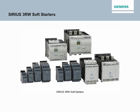Some soft starters, such as the Sirius 3RW40 and 3RW44, also allow the phase control process to be applied in reverse when the motor is being stopped. This controlled starting and stopping significantly reduces stress on connected devices and minimizes line voltage fluctuations.